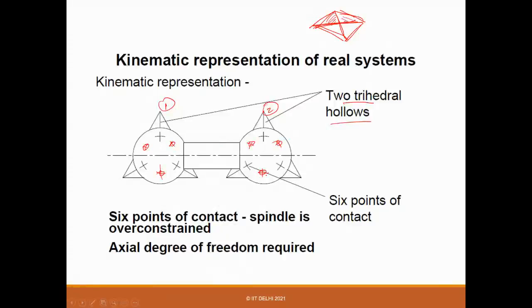And they pose three constraints, right? Three constraints on each side. So 3 plus 3, how many contacts? So total 6 contacts. And that is equivalent to 6 constraints. So ideally speaking, if it's an exactly constrained design, it should constrain all the 6 degrees of freedom, right?